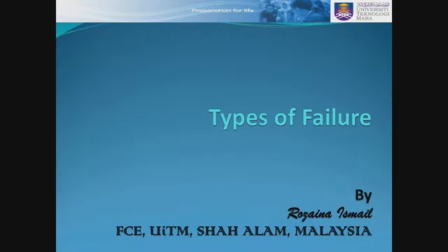Hi everybody. We are going to continue on the last topic, but not least, the type of failure due to reinforced concrete. As the applied moment on the beam section is increased beyond the linear elastic phase, the concrete strains and stresses enter the nonlinear phase.